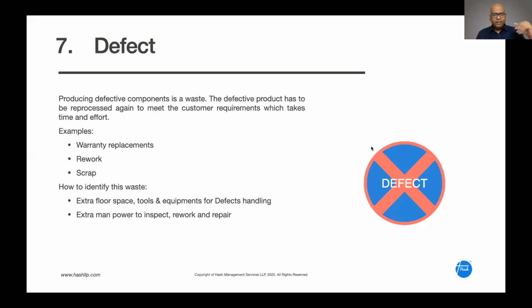But in reality, in the inspection stage, when the inspectors are analyzing a component, the moment they identify the first defect, they will keep the component separate. Right? I have taken a product. I am measuring it. There's a scratch here. So what I will do is note, there's a scratch, one number. But the same product may have another defect also that they have missed out now. Right? So what are you measuring? Defect or defective? Many people think that they are measuring the defects, but instead they are measuring the defective.